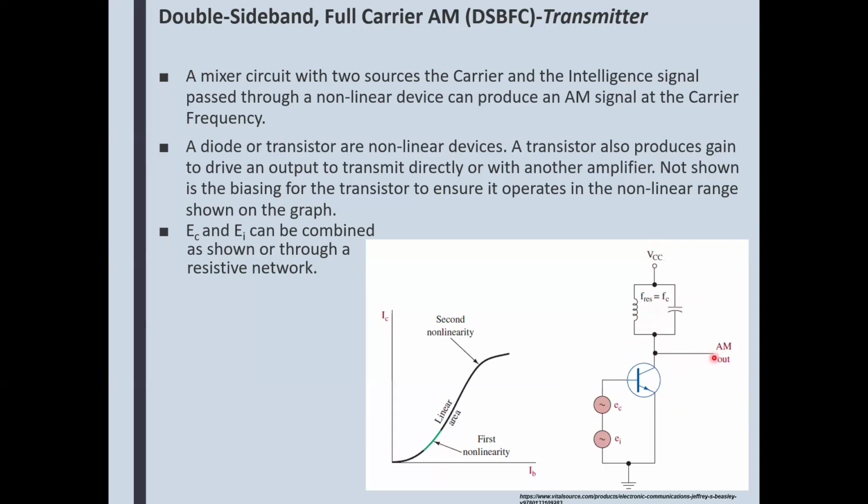So this oscillator carrier can be an oscillator producing not exactly the same frequency, but a lower frequency, as long as it does have the harmonic, which can be picked up and amplified by the tank circuit right here.